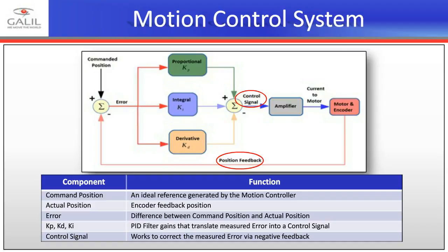Now, digital control of amplifiers involves essentially taking that motor command signal. Instead of an analog signal, now you've taken that position or torque data and you've wrapped it up in a communication protocol, whether it be TCP, RS-485, Modbus, DeviceNet, or EtherCAT.